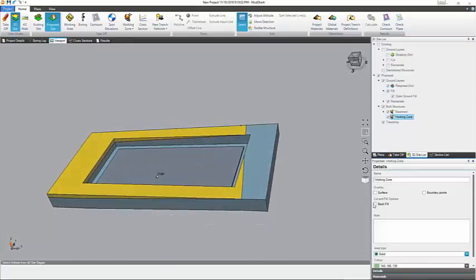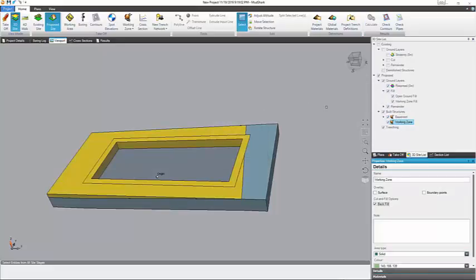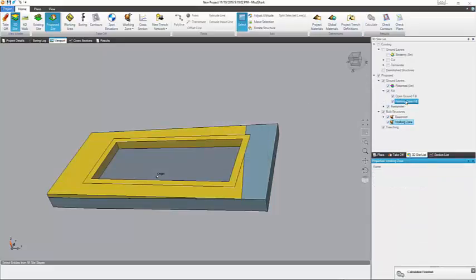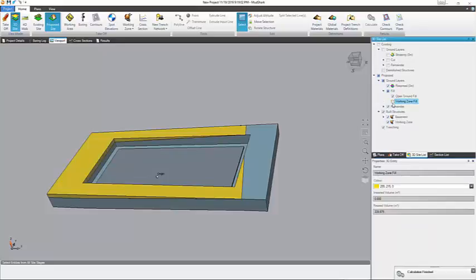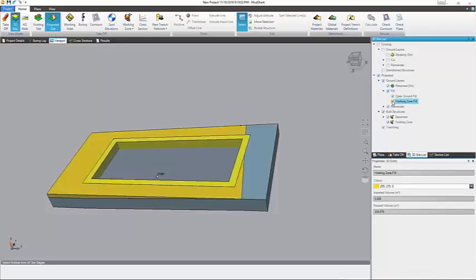But now we can go, okay, well, we've got to actually backfill all that back up to the surface after the workmen have done their job. So we can click backfill and hit calculate, and there we have it. So in our fill now, we've got our working zone fill, which is the fill to fill back up after the basement's been completed, and we've got just our general open ground fill, and we've got a hole for our basement. So that all ties together nicely and gives us our working zones.